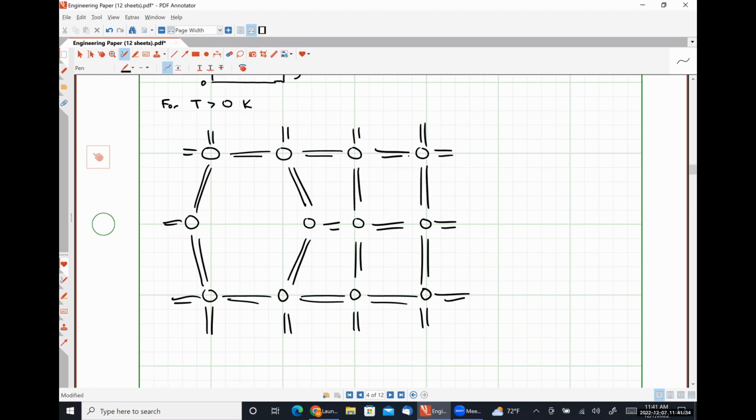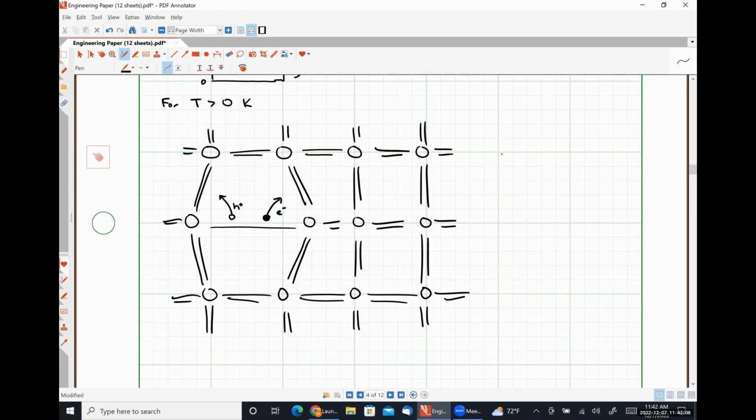Right? And sometimes, kind of like a spring, a bond might get stretched a little bit too far. So there's enough thermal energy imparted on an electron to push it from the valence band up into the conduction band. And when that happens, free charge carriers, called an electron hole pair, are generated. So on our energy band diagram, that's going to look something like this.